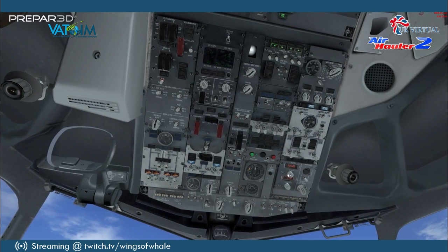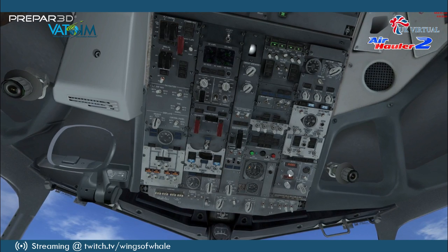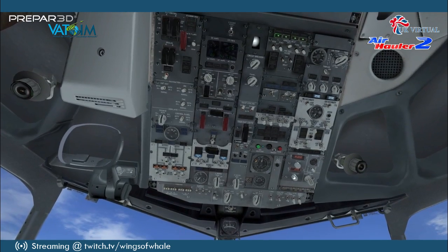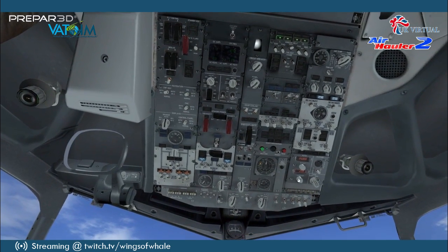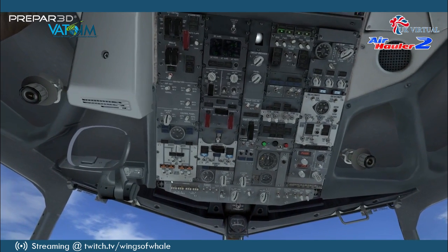This is your flight level altitude for cabin pressure. You configure that to whatever your cruise altitude is, so that the plane knows which pressure levels you're going to be flying at, and configure itself for that.